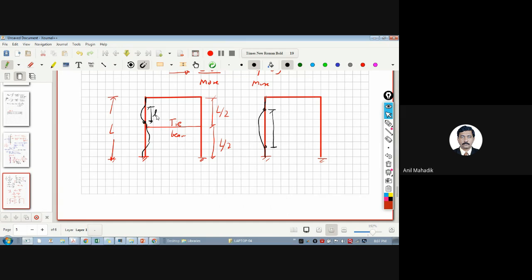Try to understand this. Getting? So effective length got reduced because you have reduced the L itself. So these are the kind of techniques you can use to increase the capacity of compression members in any practical structures. Try to understand the concepts, how we do in practice, then you can think over that.